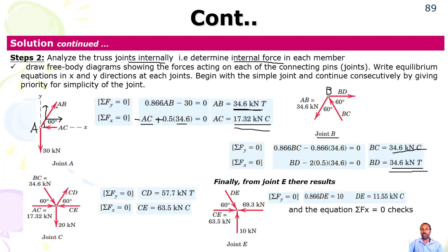So once you have AB here, which is away from the joint, here also away from the joint, which is tension. Tension should be drawn, clear? If you go to the other joint, you have to make the action and reaction force opposite to this direction, AB. This is AB. Okay, once you find this one, then you can go again to joint C. This is joint C. Then in joint C, again, you have these forces. So once you know BC and also BD, then you can proceed like this. Then summation of force in Y equals 0, CD, you can find tension, then compression.